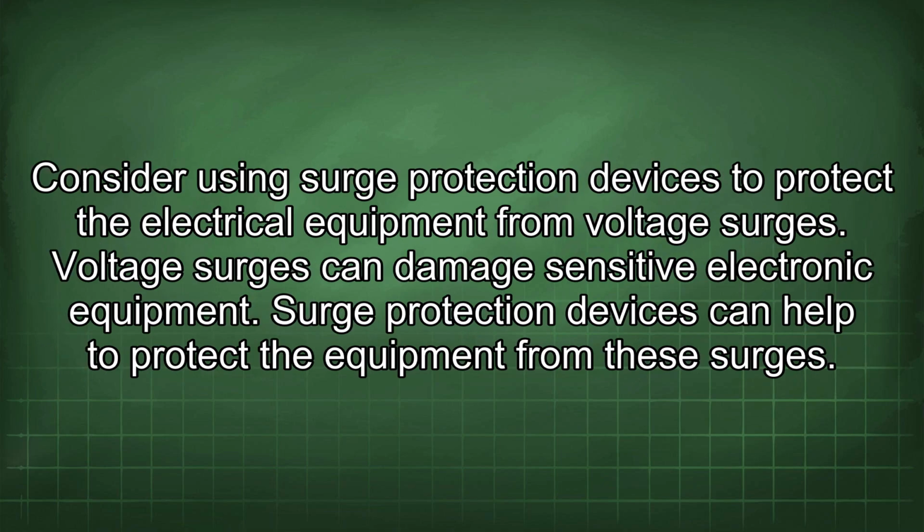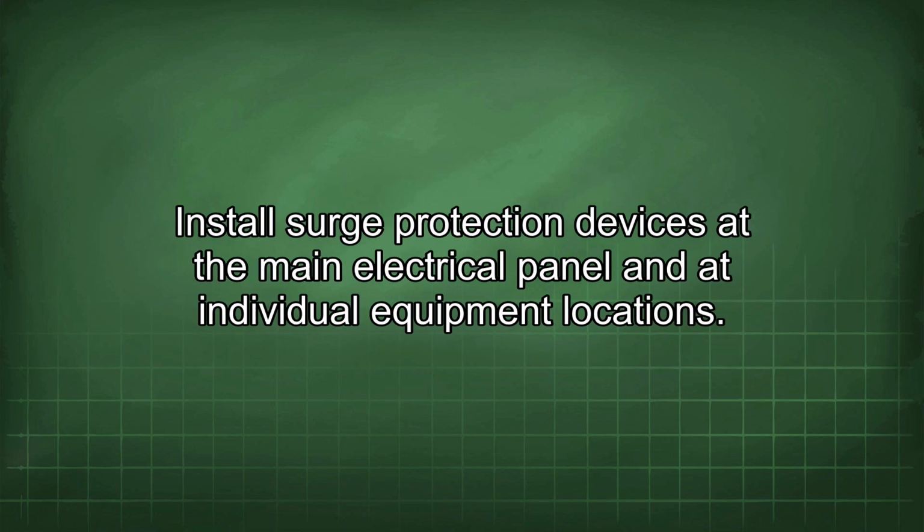Consider using surge protection devices to protect the electrical equipment from voltage surges. Voltage surges can damage sensitive electronic equipment. Surge protection devices can help to protect the equipment from these surges. Install surge protection devices at the main electrical panel and at individual equipment locations.